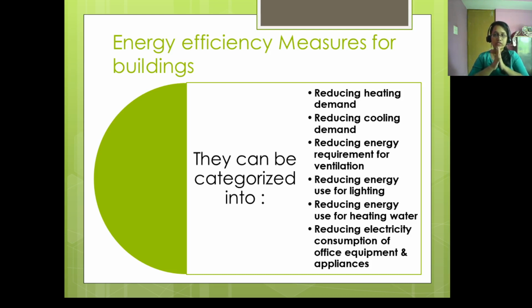Next is reducing the energy requirement for ventilation. The energy required for ventilation can be minimized by a building design that maximizes natural ventilation, then effective window design, then use of mixed mode ventilation, and using efficient mechanical and ventilation systems.